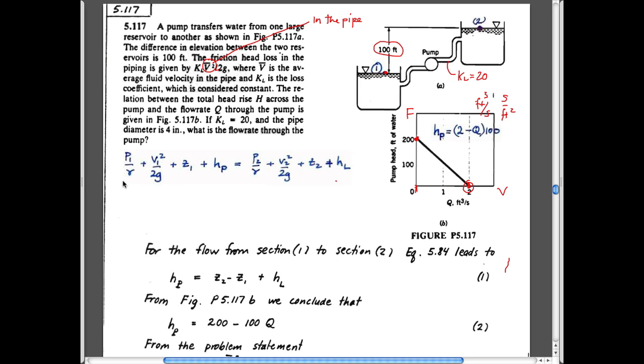This is my favorite way of writing Bernoulli's equation, always in terms of lengths, just because lengths are kind of manageable. And you know that if the lengths that you get in your problem are in thousands of kilometers, then you know you probably don't have the right answer. So these have to be in tens or hundreds of meters to make sense. So pressures. Pressure 1, atmospheric. Velocity 1, the big tank assumption. Oh, first of all, I should say, we're writing Bernoulli's equation between these 2 points.